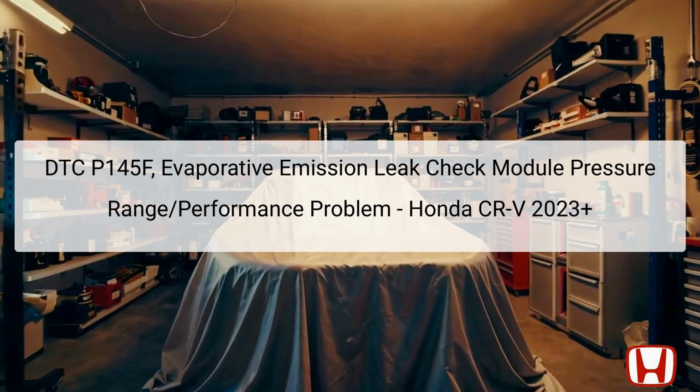The DTC P145F pertains to a performance issue within the Evaporative Emission Control System, specifically related to the leak check module pressure sensor. This diagnostic trouble code indicates that the pressure within the system has not remained within specified limits for a certain duration, as monitored by the Powertrain Control Module, PCM. The PCM is the central computer that manages engine and emission systems in the Honda CR-V, and when it detects a discrepancy, it logs the DTC.